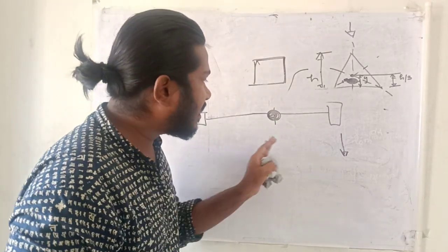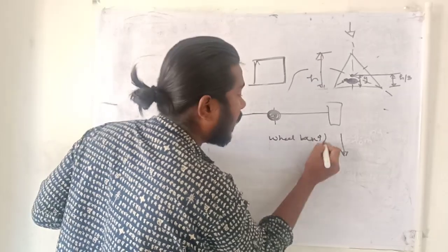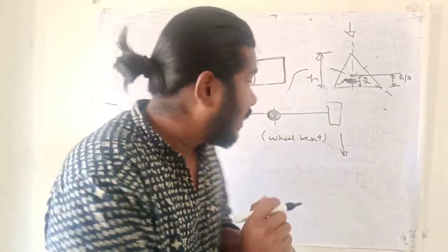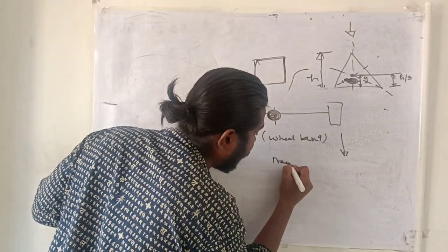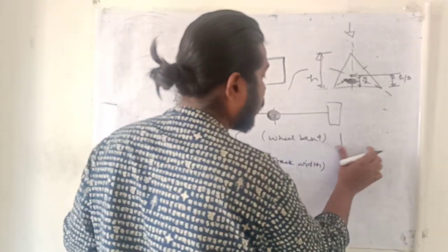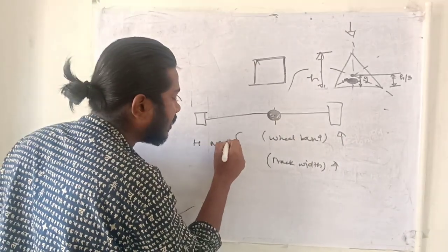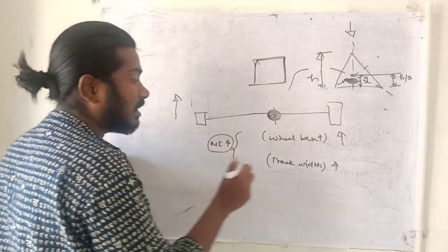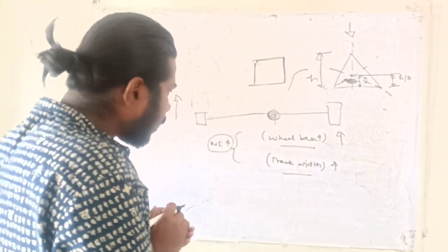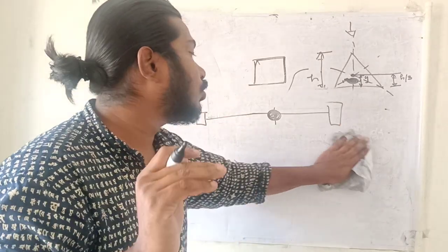Now when we talk about braking and acceleration, it means a longer wheelbase. A longer wheelbase is required. And when we talk about the distribution of forces along the right and left direction during cornering, it means we need a wider track width. To have a higher value of moment of inertia, the wheelbase and track width have to be increased as much as possible. This just talks about how, whenever we apply the brakes, our vehicle should not tip down.